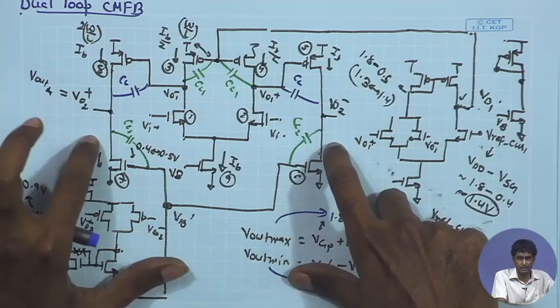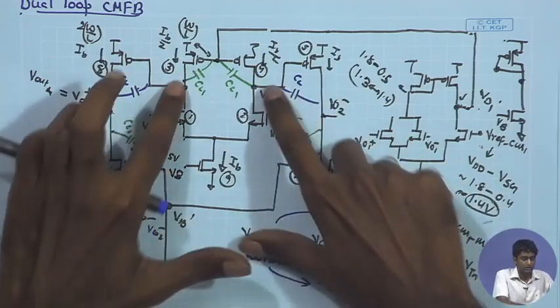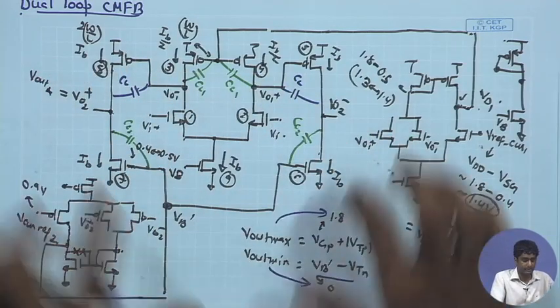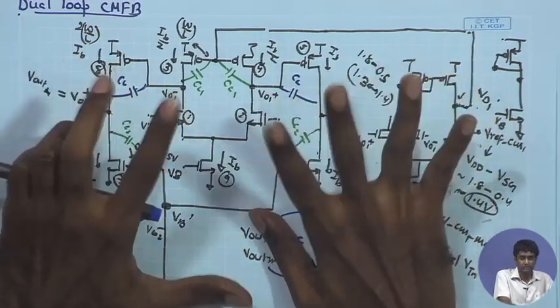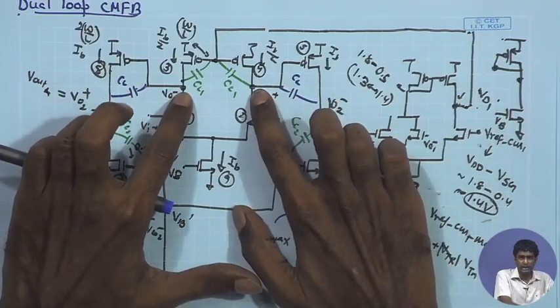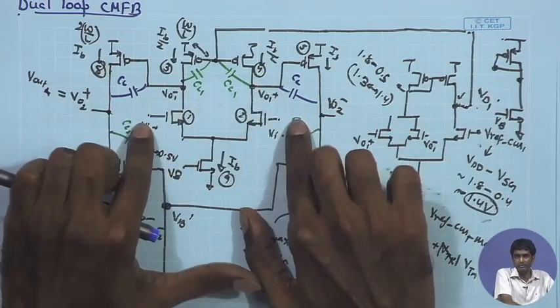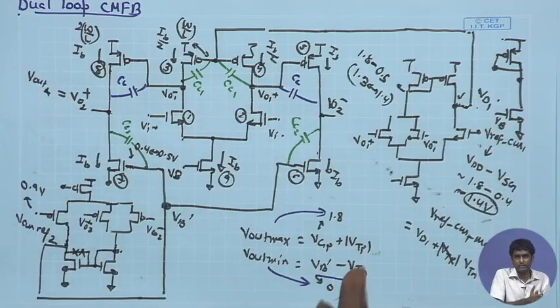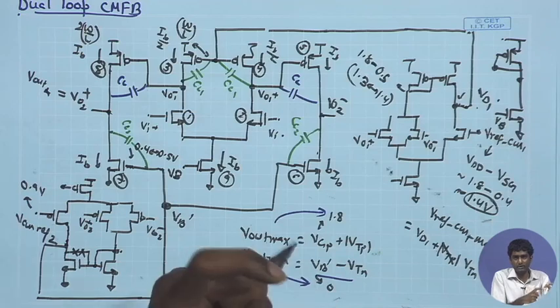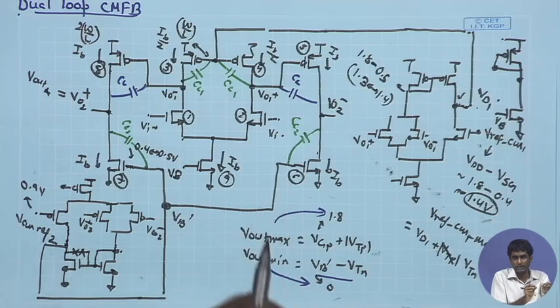And then we can check the overall differential half circuit. For the differential half circuit, I assume that the input signal is differential and the common mode gain of the circuit is poor. So, at these points you will have effectively a differential signal coming, even if the input signal that is acquired from the sensor has asymmetry. If you remember our discussion, the two electrodes are taking the signal in the vicinity of a certain area of the brain, and they are kind of close together. So, they are not acquiring exactly the same signal. Their signals can be relatively different, and you are trying to process the difference between those two signals.